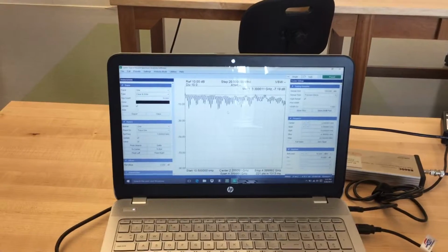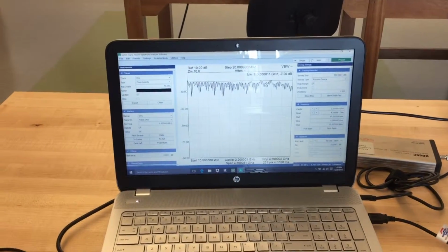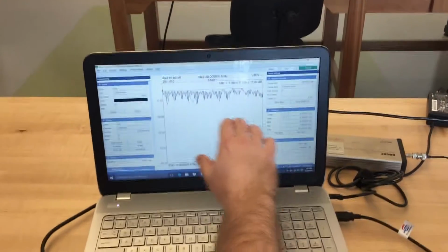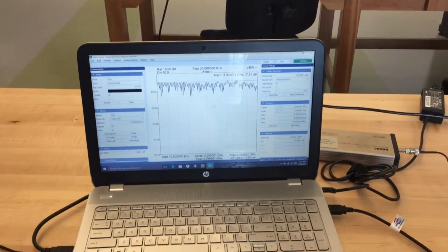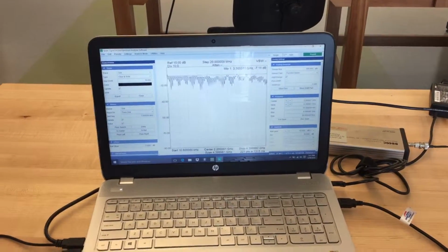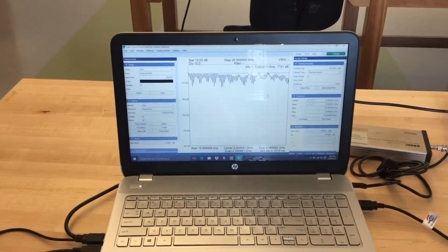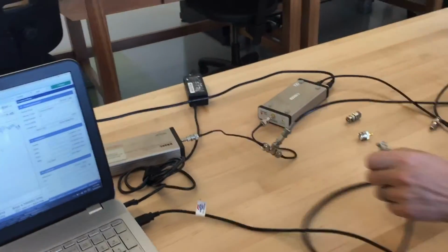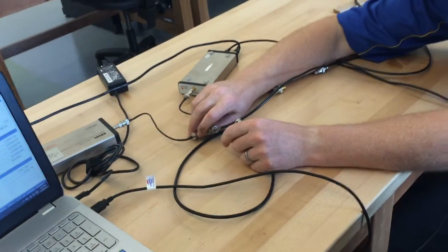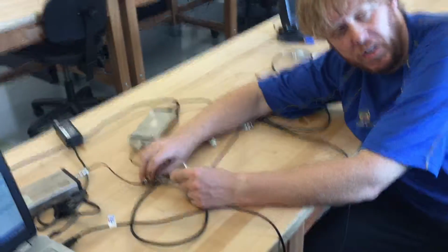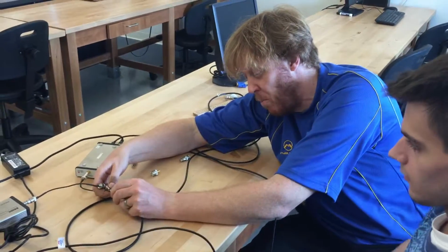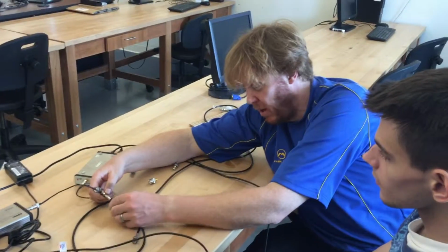What do you see here, Rob? It seems like the signal is being filtered by the cable we just put in, because that really low dip that we had is gone now. And now there's certain frequencies that simply don't get through. So it's being filtered. And that's strange. If we were to measure this cable and look at it, remember those equations we worked through in class for the quarter wave? Remember we said there's a transmission line that's a quarter wave line? Yep. Well, depending on what the frequency is, you've got a quarter wave line.